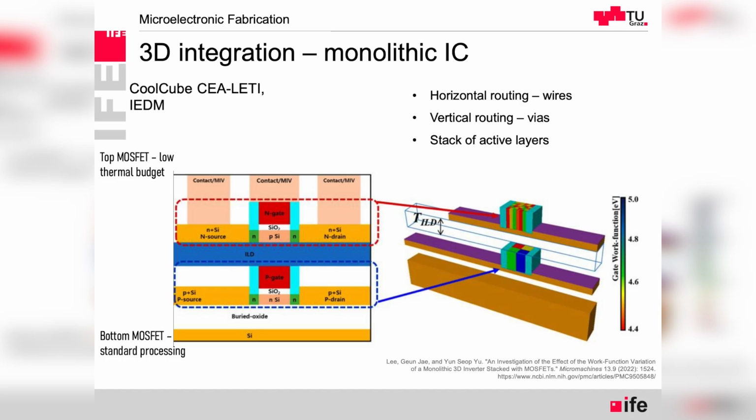It seems like a trivial idea. Why haven't we done that before? So when looking at the different processing steps for how the transistor is being made, with growing of the oxide layer, doping, adding the metallization, and so on, we could see that some processes need, for example, annealing, or in order to deposit additional layers of silicon, or including germanium, which is also epitaxial growth, that needs to happen at high temperature.